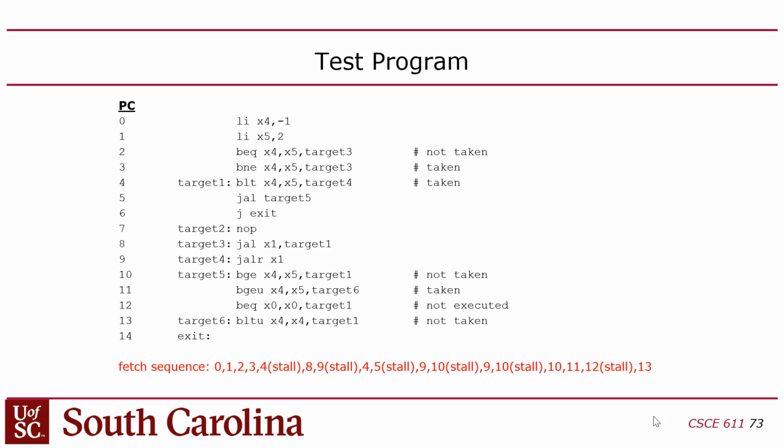So my methodology is looking at the program counter, right? And tracking the program counter as it moves through the program. If that's what you're doing, that's good enough for me. Of course, you also have the option of having your own test suite where, for example, you write a test bench that monitors the program counter automatically, right? Or you could do unit testing of individual instructions or small groups of instructions as opposed to putting this whole test program in. That's up to you.